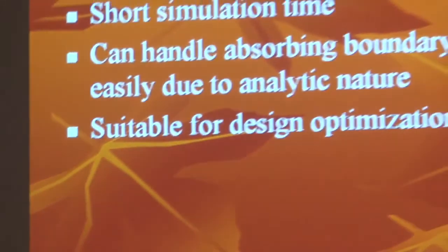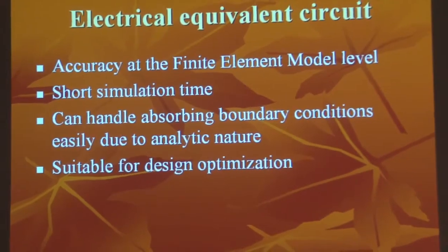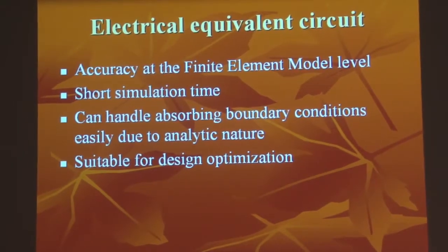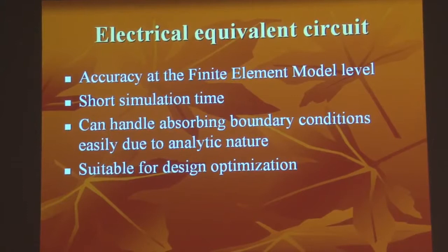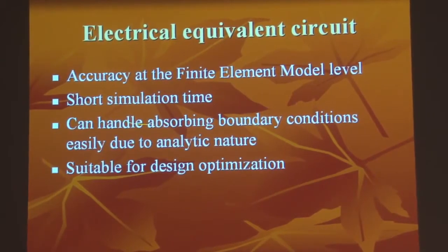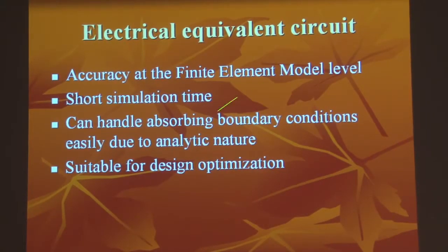We have developed an electrical equivalent circuit with an accuracy at the finite element level, very accurate. And of course, because it's an analytic model, simulation time is very short. We can handle absorbing boundary conditions easily due to the analytic nature of the formulation. And also, because the simulation time is so short, it's good for design optimization rather than just verification.